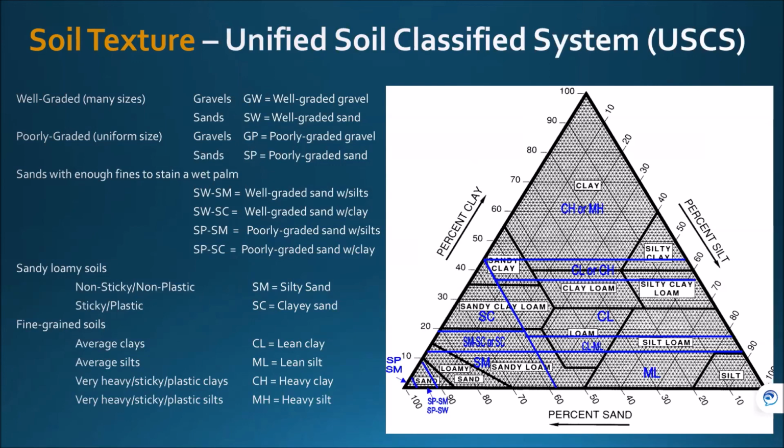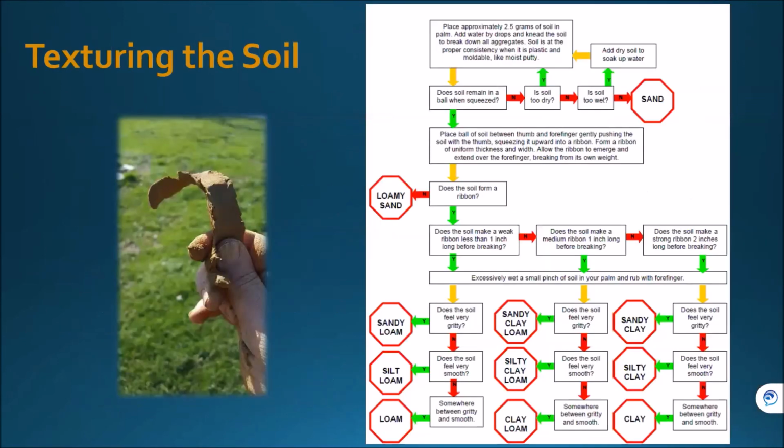The textural triangle that you see there has the USDA texture triangle behind the blue, and I hope that you can see the blue Unified overlaid on that. Like I said, it's just a more general grouping based on how those soil particle sizes and textures can be manipulated. So when we do the reports, we make sure that we include both of those for submittal to the construction folks. Next slide, please.